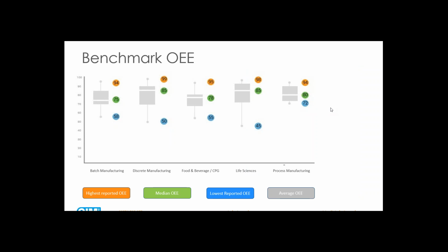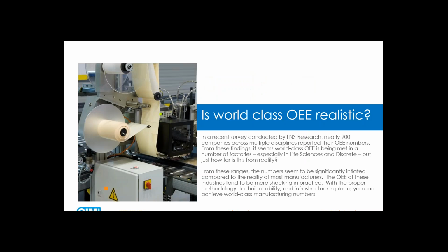Well, the first thing I think it tells us is that people are artificially inflating the OEEs they're recording, because very frequently I'll see companies within the same sectors, in the same industries, that in reality, if you were measuring OEE to the book, would be more like 30 to 60. So it's important to take benchmarks or world-class OEE with a pinch of salt and set yourself an appropriate target.